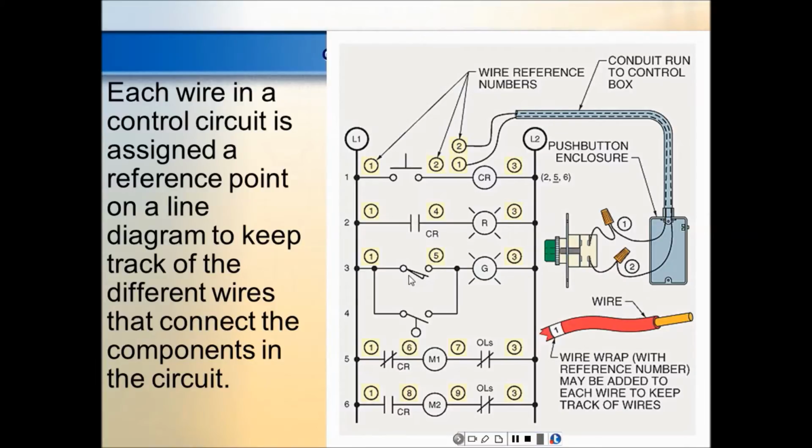And why is that? Because of vibration, and heat's the biggest problem. They get a little hot, they expand, they cool, they contract, and eventually they'll work themselves loose. You cannot put more than 2 wires under the same terminal. Never.